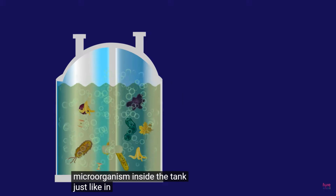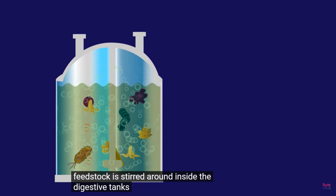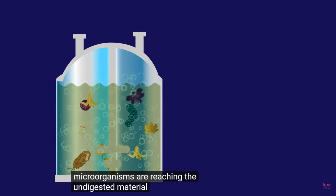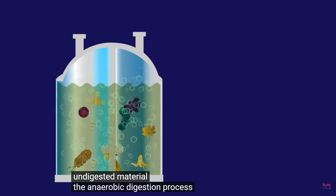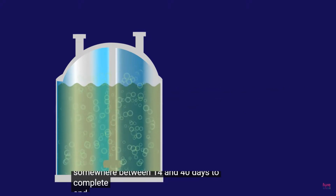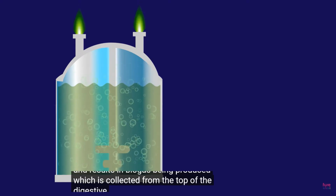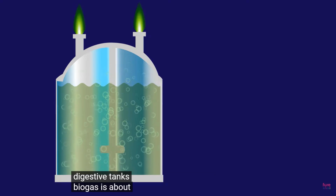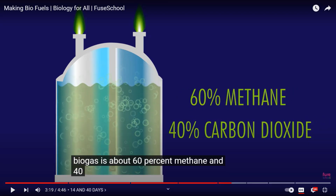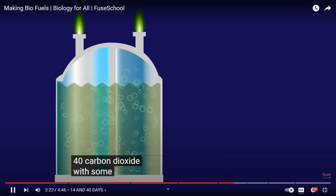Just like in your digestive system, the feedstock is stirred around inside the digester tanks to ensure the microorganisms are reaching the undigested material. The anaerobic digestion process takes somewhere between 14 and 40 days to complete, and results in biogas being produced, which is collected from the top of the digester tanks. Biogas is about 60% methane and 40% carbon dioxide, with some other trace contaminants.